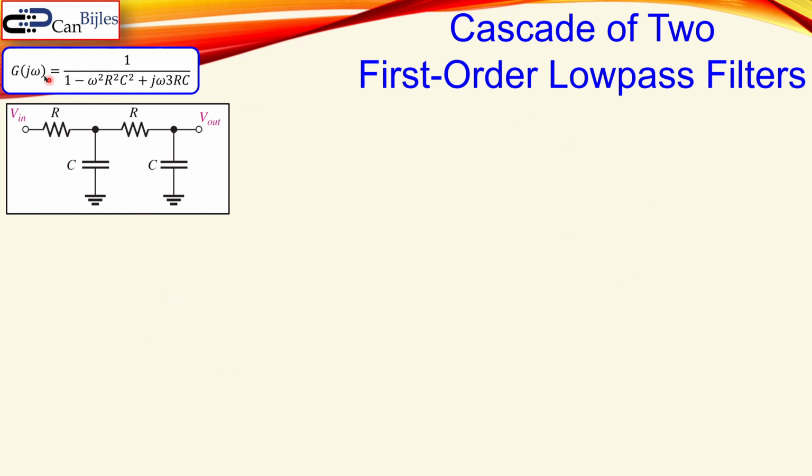Okay. Now let's also look at the situation for the cutoff frequency. So the cutoff frequency for this circuit, where you have this transfer function, can be calculated using again the definition, because we know the absolute value of this G for this circuit, the transfer function. If we equate that to 1 over square root of 2, we can go to the omega we want, which is the omega cutoff.